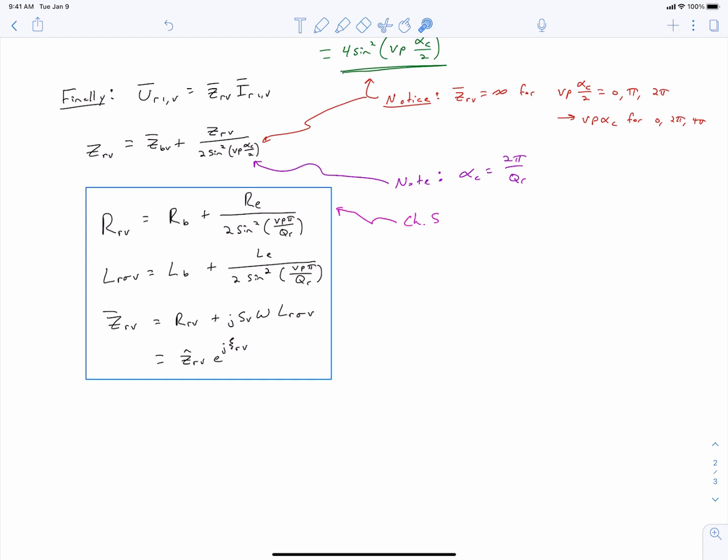And when you are at a locked rotor condition, your frequency conditions in the rotor are high because S is equal to 1. But when you are at rated load or at no load, S is typically very small, and then your frequency is low. So chapter 5 will tell you how to calculate your resistances, and these leakage inductances, see section 4.3 of your textbook. Okay, so with this observation, we can start to notice that our electric circuit becomes very simple.